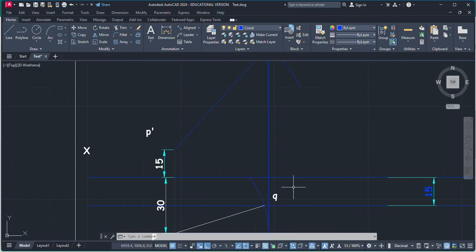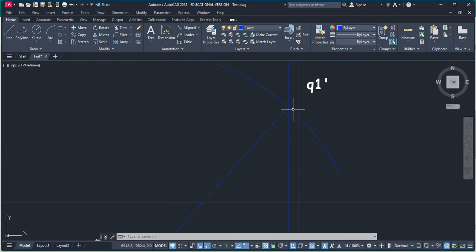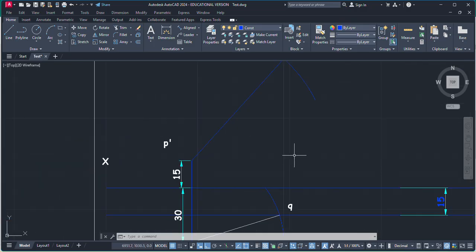So now we have the true line here. From this point of intersection, I'm going to draw a locus, because we know the endpoints of the true line and apparent line always appear on the same horizontal line. So now I'm going to use that particular shortcut in which end points always lie on the same vertical line.